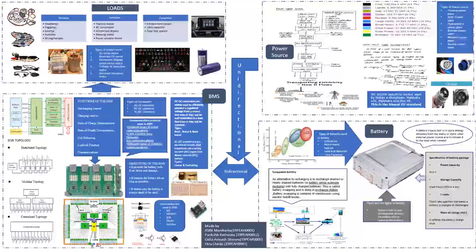If we are supplying 1000 megawatt at 30,000 volts, the ampere rating will be very high. To transfer that amount of current, we would need so many bundles of electric wires. That's why we step up the voltage and reduce the ampere rating, and we can transport the electricity within limited electric wires.